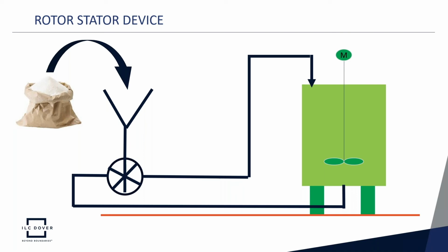However, the increasing volume of powders now being processed have exposed the weaknesses of this device, the most significant being the noise from the large motor, limitation on ability to move certain powder types, the need for regular cleaning because of blockage, and a design that does not facilitate easy cleaning, it having a moving part at the heart of the system, so some disassembly is required.